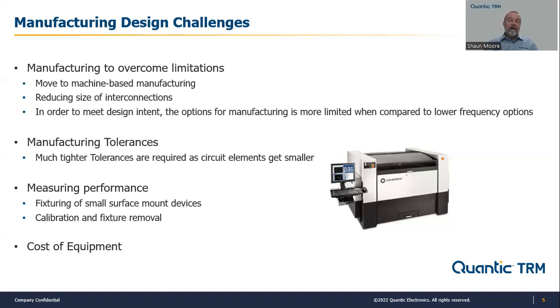So therefore, the ratios kind of work out okay. So we can go in there now and start using some different manufacturing technologies to get the tighter and tighter tolerances that are required, basically just to maintain the same sort of variability of performance that we have at lower frequency, sub 20 gigahertz sort of performance, moving up into Ka and above.